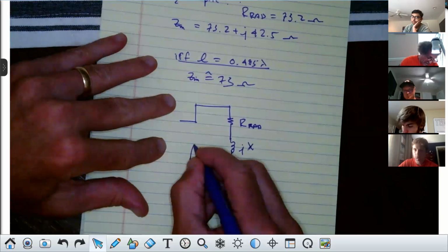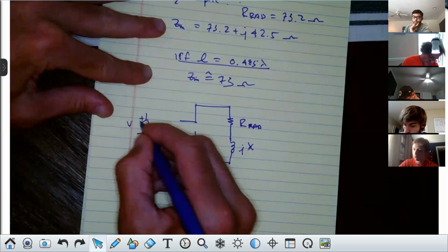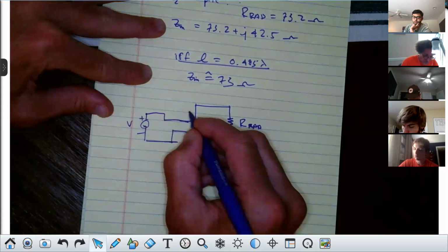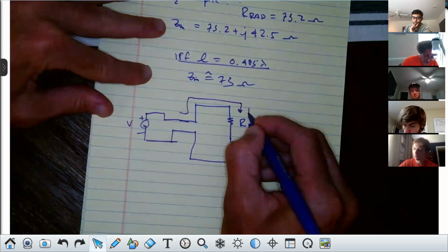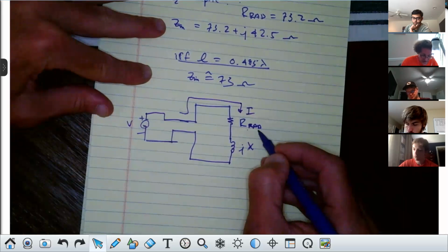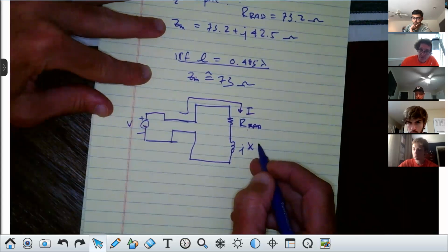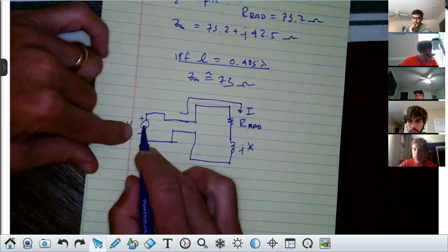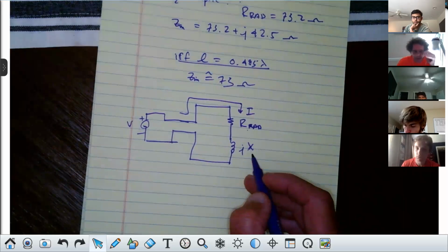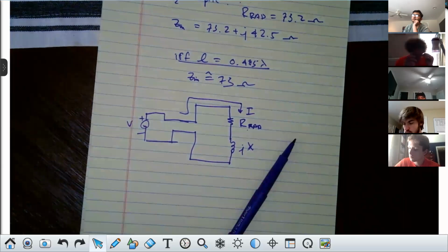You would like to get rid of that because when you have a voltage source here, plus minus V, and it's driving this, remember, it takes current going through here, 1/2 I squared R rad. That's where all the power comes from. The current flowing through the reactance doesn't do anything for us. But that voltage, in order to get the power you want, will have to overcome this resistance and that reactance. Got me?